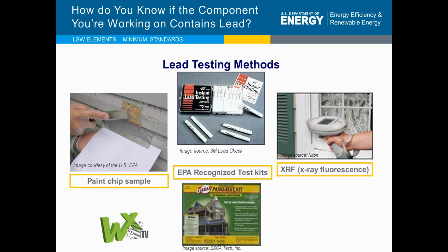On the other hand, if you need a quantitative level of lead, as of October 2011, EPA does permit paint chip sampling, and that's a quantitative method of which you have to work with a certified lab, and there is a list with EPA that they will provide you as far as that particular lab. You can hire someone as well if you want to do X-ray fluorescence testing.